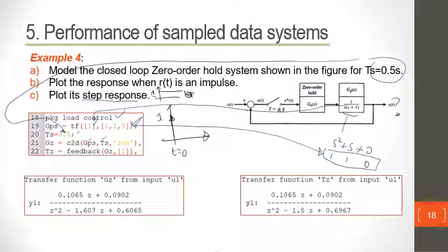Sometimes we can explicitly state that we are using the zero order hold, although by default it will just do a zero order hold even if you don't put this as an argument, as initially shown. Because you can have different types of holds. You can have a first order hold, a second order hold, which we will not discuss and are beyond the scope of this module. But you do that, so this gives you a G(z).